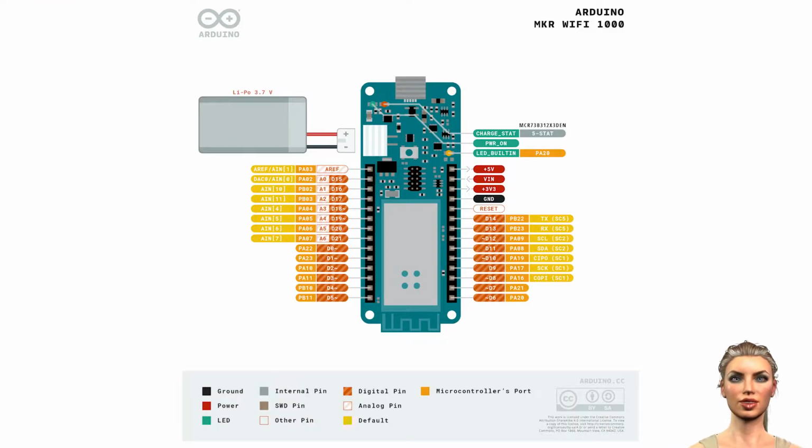I have chosen this Arduino model since it incorporates many interesting features, such as a low-consumption microcontroller, with 32-bit computing power, built-in Wi-Fi and Bluetooth connectivity, without the need for additional shields, a recharging circuit for an external lithium polymer battery so that the board can work without mains power, an output pin to generate an analog signal, 13 pins to generate PWM signals, and many more features.